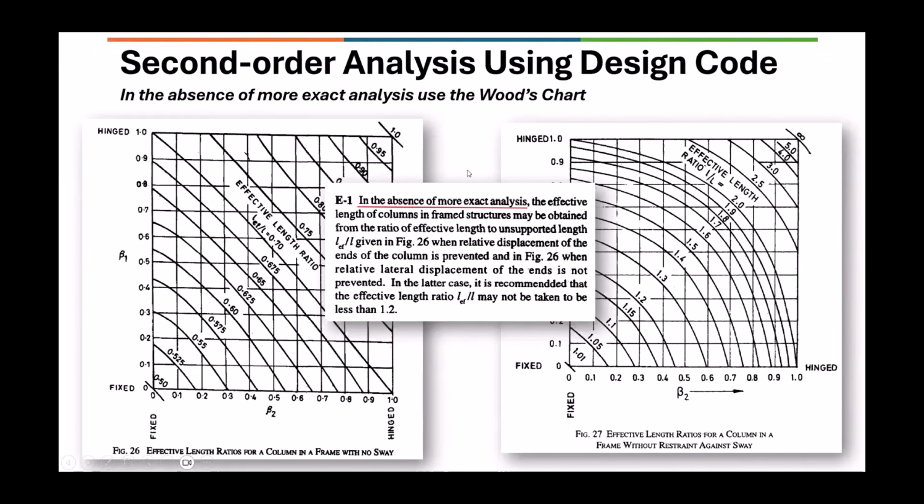So we generally use the approximate effective length factor methods for sway and non-sway. So the classifications, all that is utilized in the design stage, not in the analysis. So your primary analysis is not capturing the second order effects. Now, when you do the P-delta analysis, these are captured.